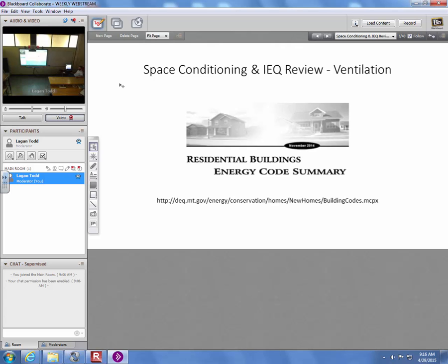That is more complicated. If you follow the guidelines of ASHRAE 62.1 and 62.2, you determine that ventilation rate based on the number of occupants as well as the square footage of the building. The CFM per occupant varies from, I want to say 5 at the low end up to maybe 20 at the high end. So in a gymnasium where people are very active, or some kind of fitness center, they're going to require more CFM per occupant than they do in a library where people are more sedentary. In a classroom full of active little kids, it's higher than in a library.